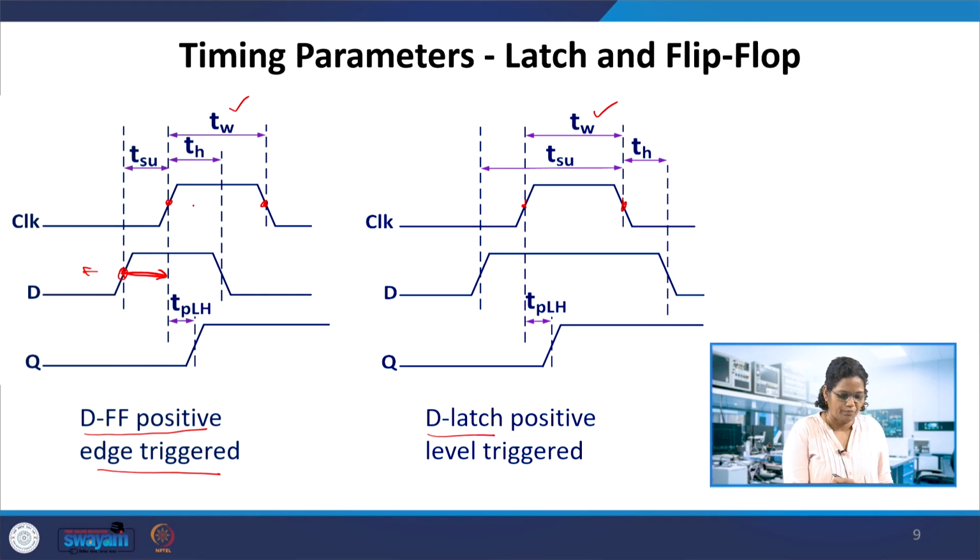There will be a window for the flip flops, the setup time and hold time, during which the data should not be changing. Similarly, the active edge of the clock is considered here, and this hold time is TH, where after the clock has become active, we look at the time at which the data is changing. Here this is TH. Okay, so this is the hold time for the flip flop, setup time and hold time.